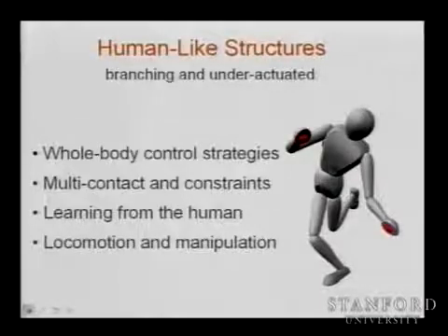We're not talking about contact with one end effector. There are many different points you are controlling. You have multi-contact. You have many constraints. You have a lot of things taking place. And you really need to deal with all of these simultaneously and in a coherent fashion. You cannot pull in one direction without really accounting for what is happening in other directions.